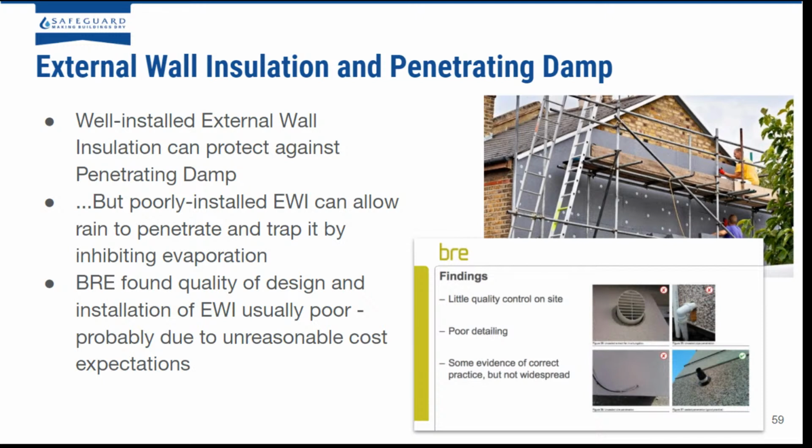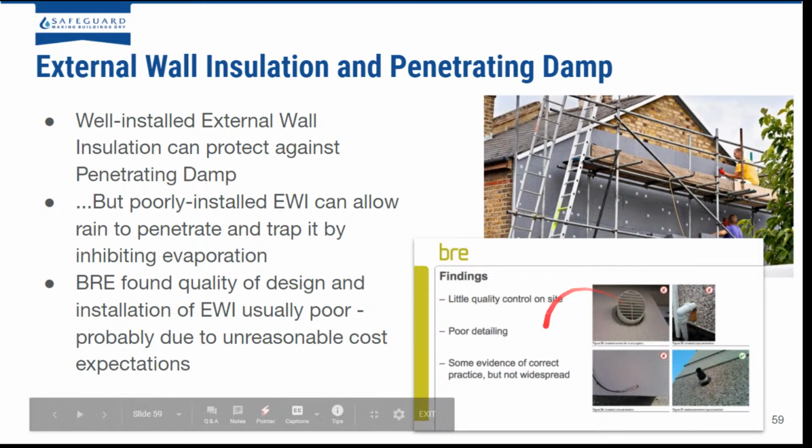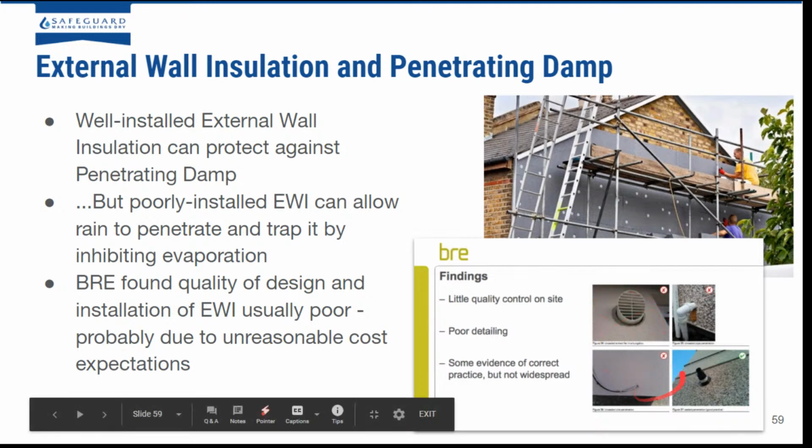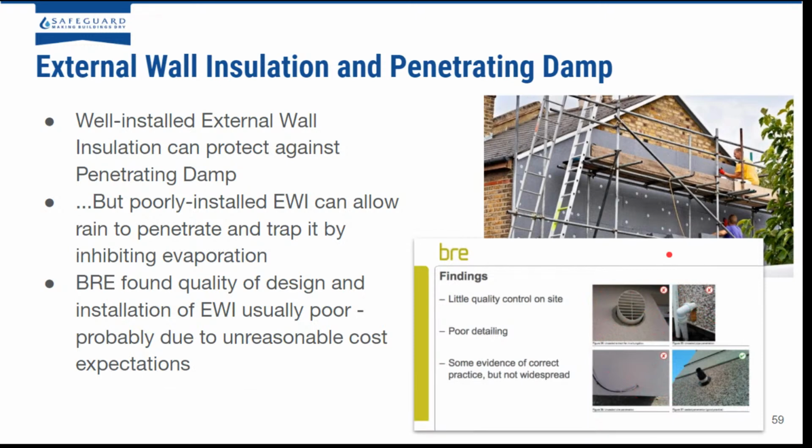So the BRE, the study that they found, quality of design and installation of EWI was usually quite poor, especially with detailing, probably due to unreasonable cost expectations and it being carried out too quickly. So if you are getting EWI installed, make sure you pay attention to the detailing and get that right so that you don't trap penetrating rain behind your EWI.